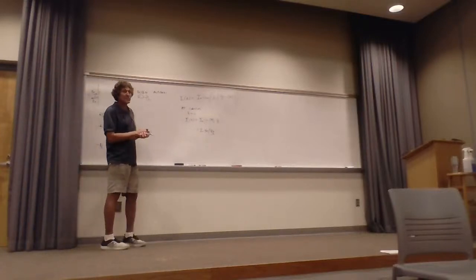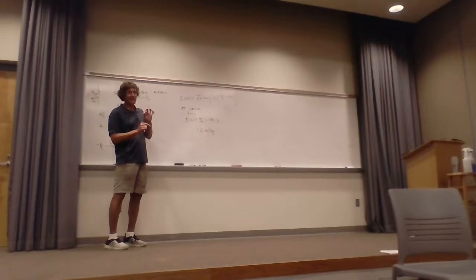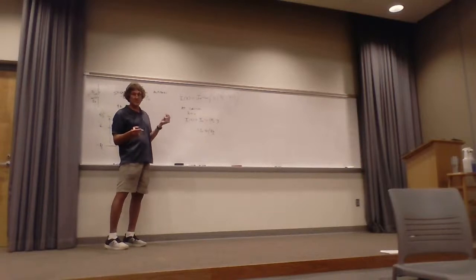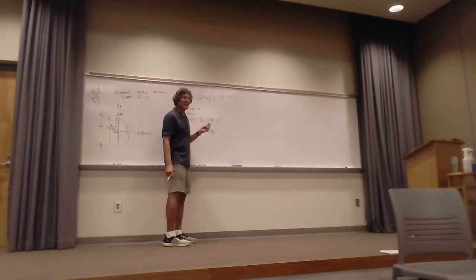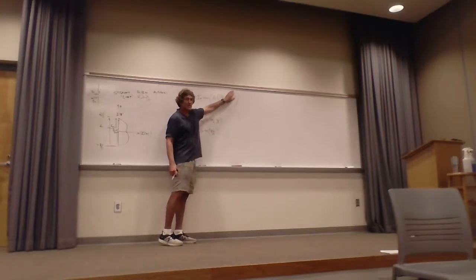So you can see that when it's exactly a full wavelength, the current theoretically goes to 0 right at the top, the feed. It never goes to 0, but it gets low. And by the same token, if your antenna is equal to lambda over 2, just take a look at this. If it's lambda over 2, it's when Z is 0, right? If Z is 0, we're going to take a look at that current.